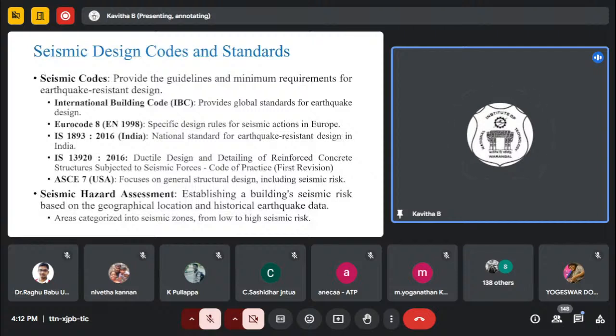One more code is also important, IS 13920. This is the ductile detailing code. Although you design your structure properly, this ductile property of the building is going to ensure that even in an earthquake, your building can sustain a little bit longer. That is the second thing. So if you want to start designing, download one of these two codes, it is going to help.